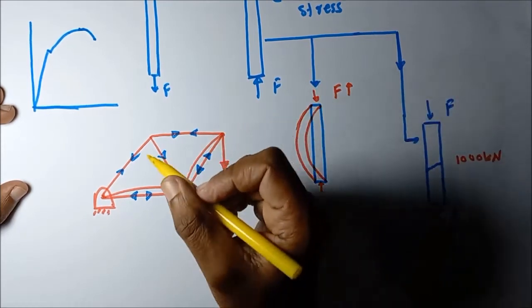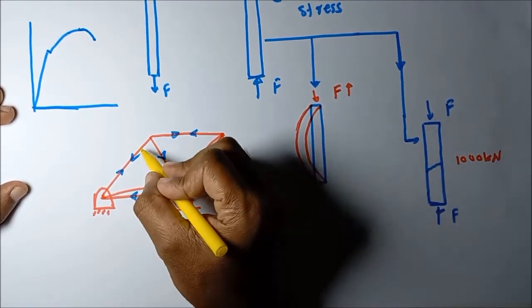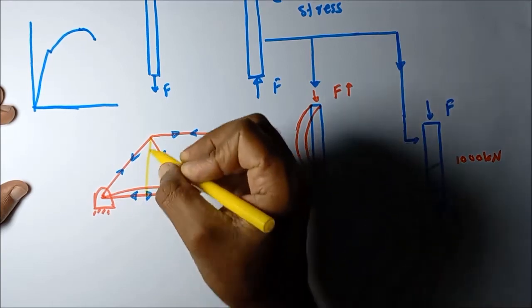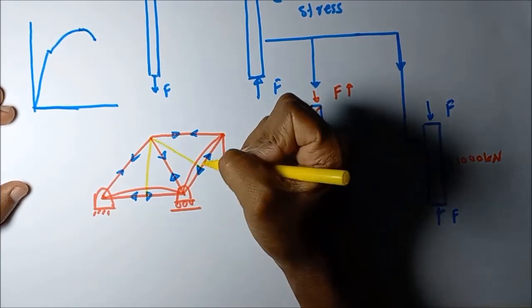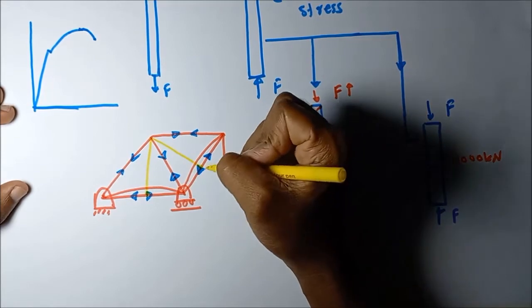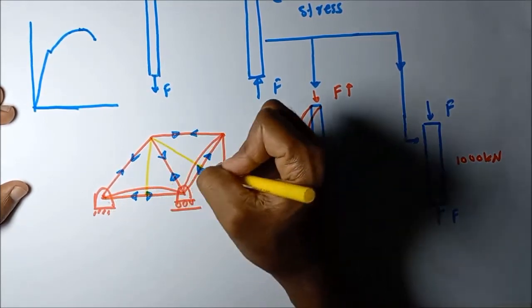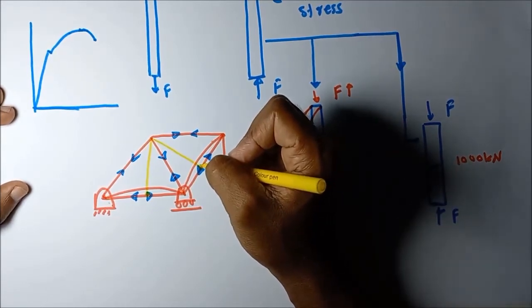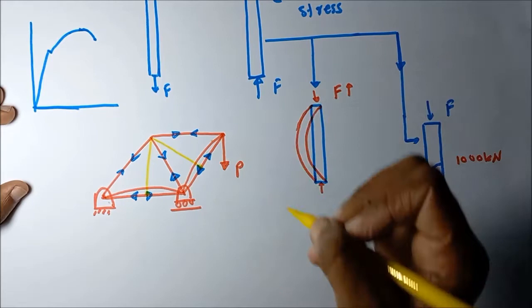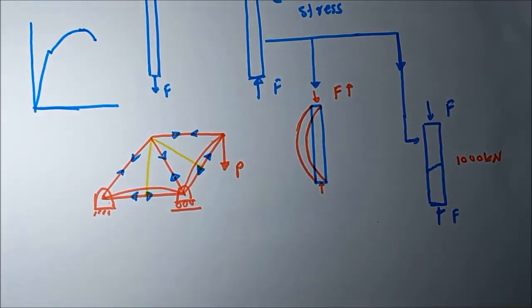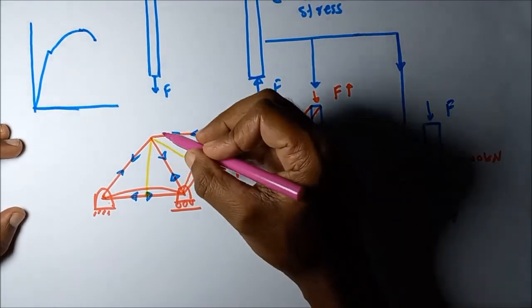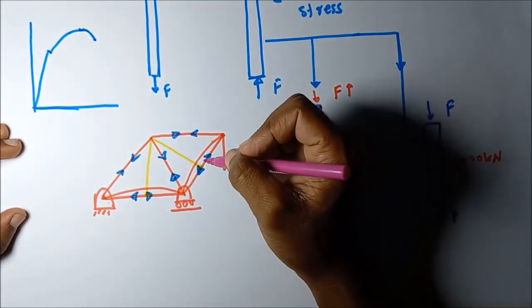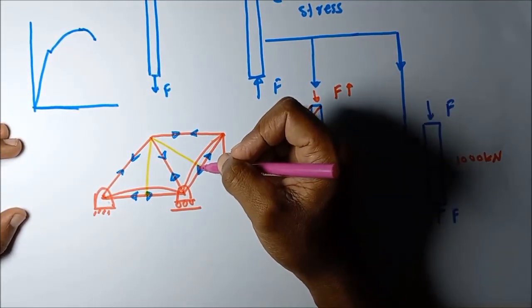Okay. Then to avoid this kind of buckling in a truss structure, additional support members are added to the structure. That means this will give lateral support to this bar element. Then the strength increases. That means the buckling load can increase by giving the lateral support. Later we will discuss this one. In most cases, this kind of idler bars are inserted into this kind of truss structure to strengthen the structure against buckling failure.